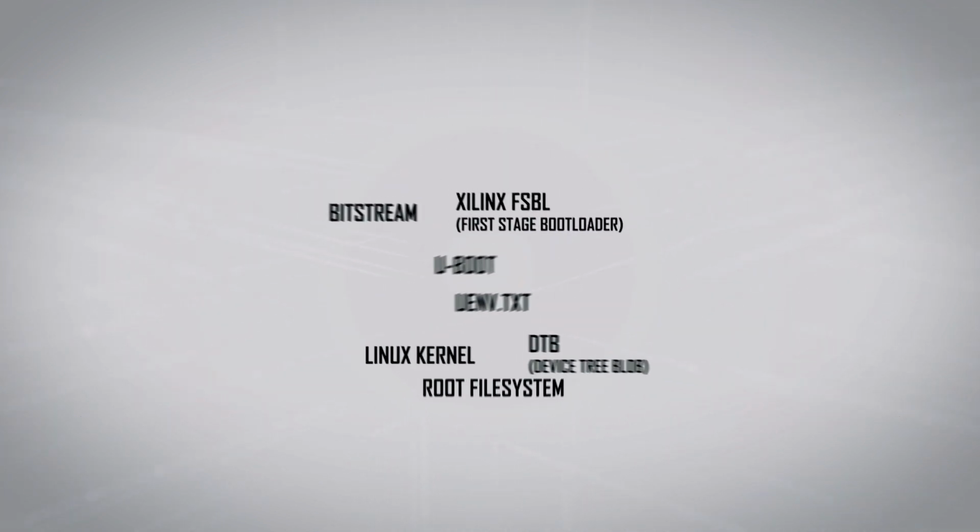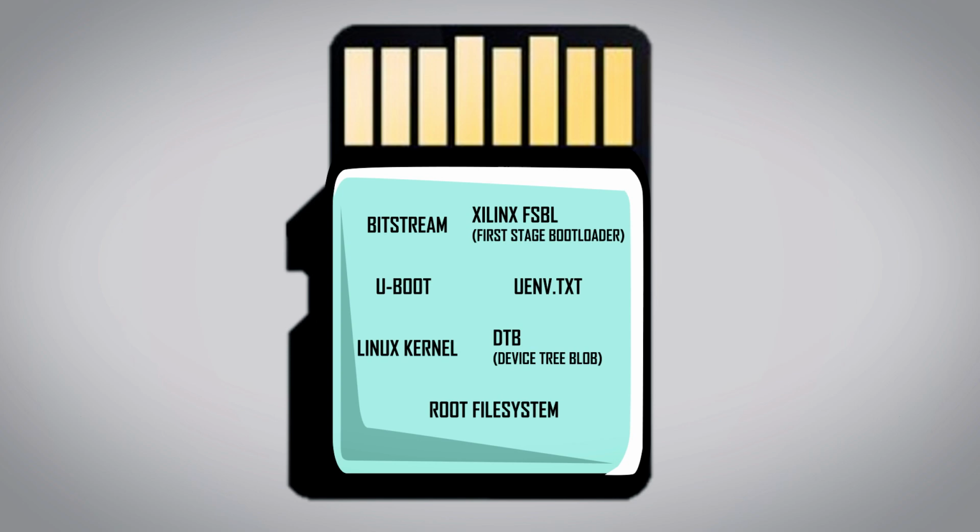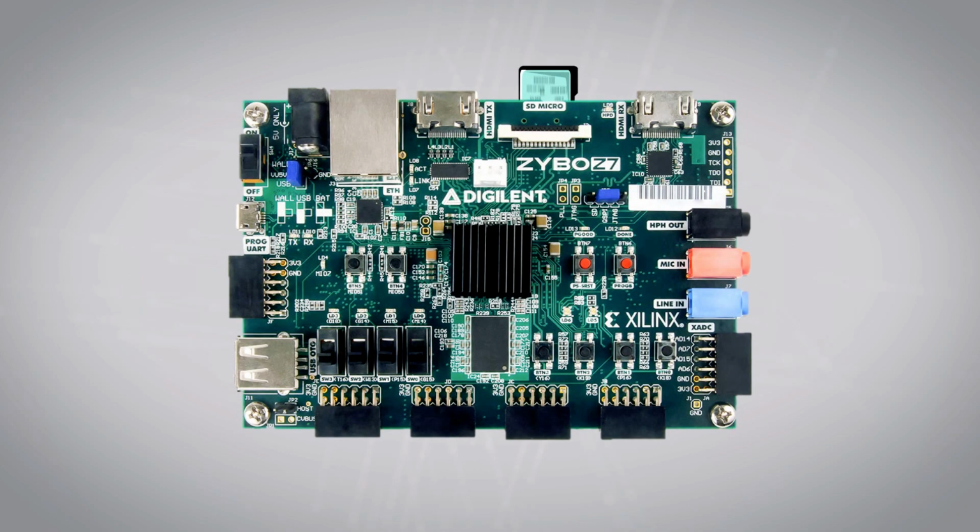All of these OS components will need to be on the micro SD card so that we can run our custom OS on the Zybo board. So now we know exactly what we need. I'll switch over to my Ubuntu desktop so we can start generating all these OS components.